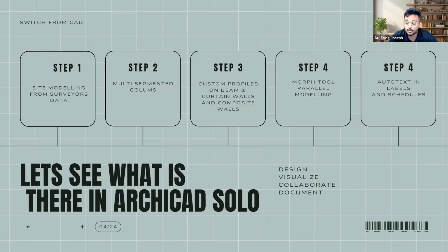Next, we will be looking into some of the attributes of Archicad, which will help you to document completely, which is the highlight when comparing modeling software to BIM software. Again, we'll be looking into a tool called the Morph tool, which is going to help a lot in making a massing model and even creating certain objects or libraries for us.